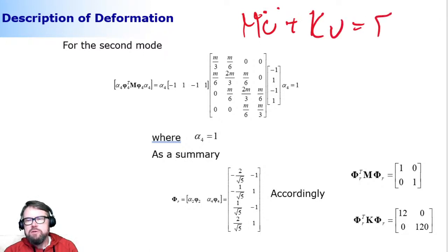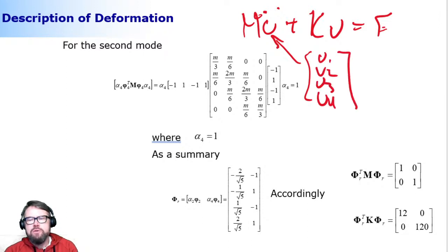When using the model reduction, I'm originally going to have here 4 components, which are U1, U2, U3, U4, and the corresponding mass and stiffness. And now when I'm using model reduction, I'm first computing the eigenvalues and eigenvectors, and I'm selecting 2 eigenvectors.